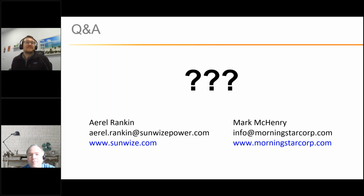It's hard to answer in a general time. It's hard to say, oh yeah, for sure you'll get 2 years under these conditions, because it just depends on the battery manufacturer, the quality, there's varying degrees, and also the temperature extremes you experience. In general, if you're cycling in the cold a lot, like below zero, you're likely to see less, and same in the extreme heat, you're likely to see more derate or degradation of the battery over time. But tough to say an exact time.